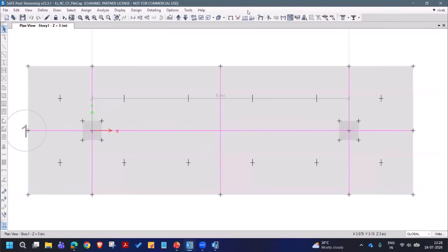Can we design strap beam footing in SAFE? Yes, you can do that. Our recommendation is, instead of the beam modeled as frame in the current combined footing which you're seeing, you can model them as a shell element. So just draw an overlapping, let's say 1 meter wide strap beam and depth is 1 meter. You can define a shell of 1 meter thick and draw this connecting the columns or extending beyond that.